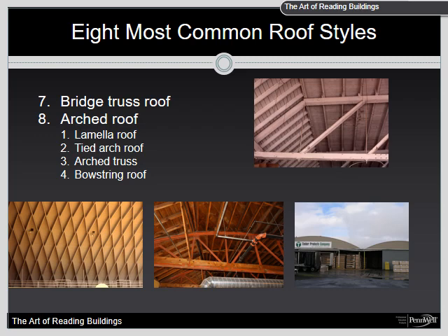First, the arches terminate on the foundation of the ground. Second, the roof is supported by exterior walls that are supported by exterior buttresses. And third, in a few instances, there is an internal tie rod with a turnbuckle. It is common on gymnasiums, recreational buildings, large supermarkets, and some buildings that may be considered medium size. Strengths. Lamella roofs are solidly built, possessing good construction techniques and lumber. The strong area of the roof is at the perimeter of the building.